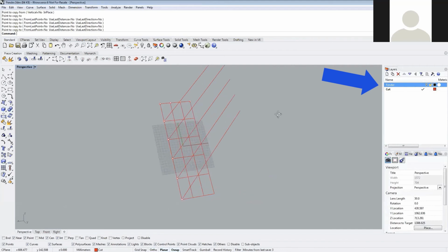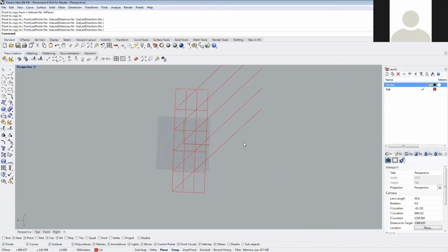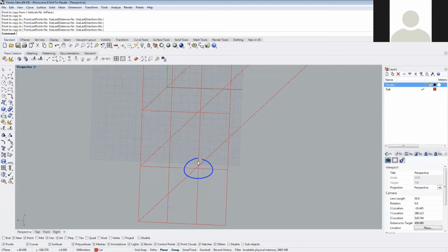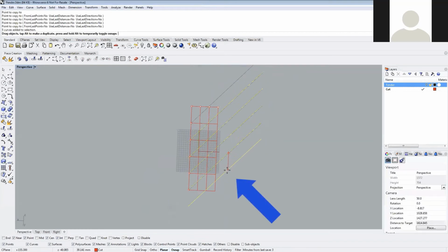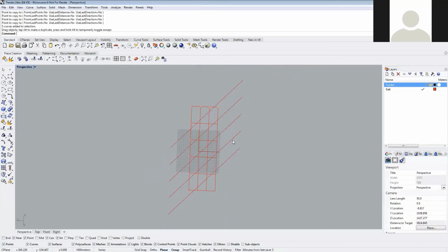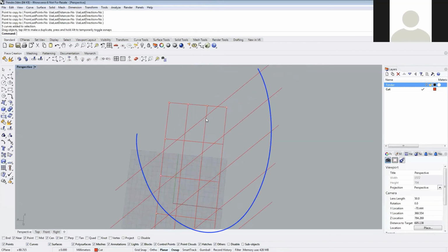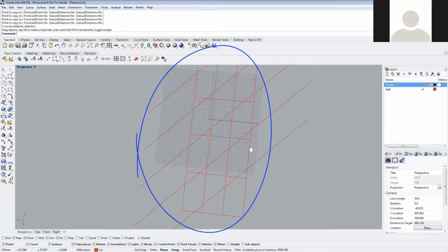We're going to turn off our meshes. This allows us to examine where our different plies are all going to intersect. So we can see we're very close to intersecting at the same point over here. So we might want to, we'll select our bias curves, and we're just going to manipulate them. I'm going to hold shift so we're translating this perfectly horizontal or vertical, but we don't have to. So long as our curves all intersect the bounding box, there's nothing wrong with that. I'm actually going to hold Alt on the keyboard just so I'm not snapping to anything, and we'll just move our curves there. So when we look at them now, we're not intersecting at a common point, so our different layers are not going to have any kind of gap right through.